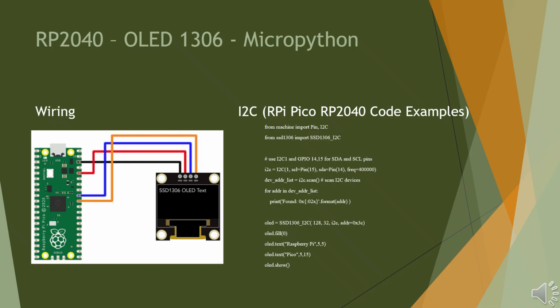First, the script imports the necessary MicroPython modules: machine for hardware control, ssd1306 for the OLED driver library, and utime for timing functions. These libraries give the Pico direct access to its I2C bus pins and to standard display commands. Next, the code initializes the I2C interface.